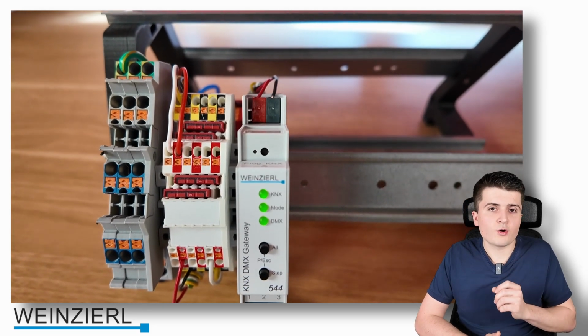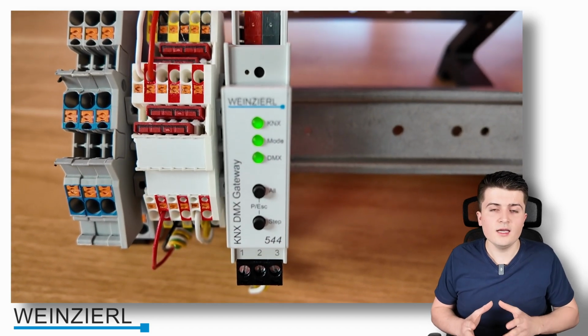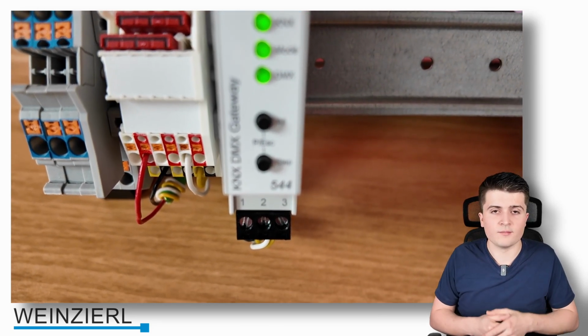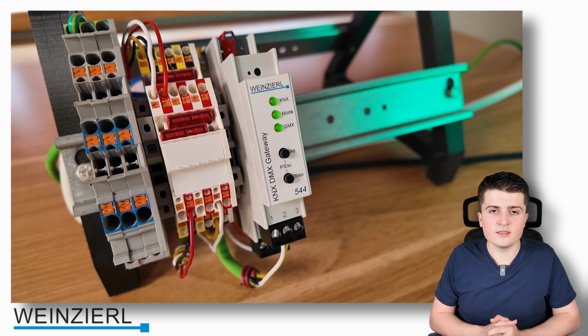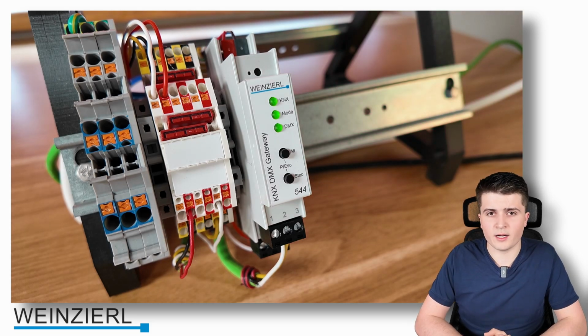And here it's really important that you use a separate 24 volt power supply and not the secondary output of a KNX power supply, because this secondary output isn't galvanically isolated and normally also has 30 volts. So this is something that you have to bear in mind.